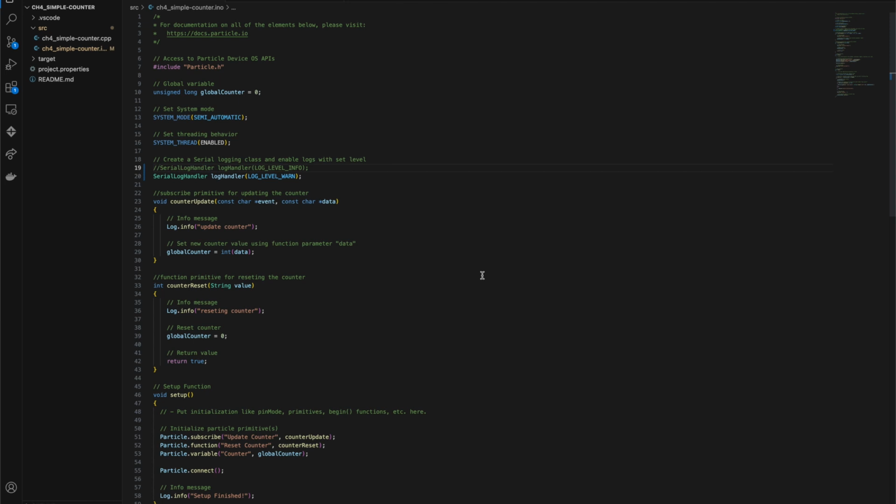The key point to highlight here is you can add a ton of various messages and levels throughout your firmware. Then you can either segregate messages based off the level, or turn off all messages when the firmware is ready to be released by setting the logging level to off.